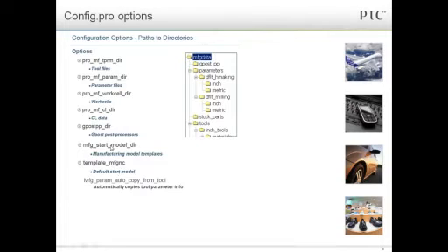And then also, if you do metric machining and English machining and machining for customer A and machining for customer B, and there's a lot of different scenarios that you could map to this idea, instead of you having to choose one every single time, you could put all of those different styles of start parts or different ways that you want to machine, and again, you could do a lot of different stuff with this. You can put them essentially into a folder, and as long as you uncheck that template button when you said file new, you would get a list of those, and then you would get a choice of the one that you want to use.